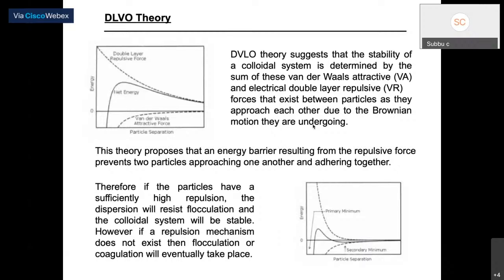The reason is that, because of the viscosity effects and hydrophilic, hydrophobic effects, you are not allowing two particles to come closer. That means you are decreasing the attraction forces. Because of that, the net force has now become still towards the repulsive, so the particle doesn't settle down. "Sir, how do I understand this?" You look at the attractive forces and the repulsive force, and the net force is shown in the center of the curve. The net force is the one that is dominant.